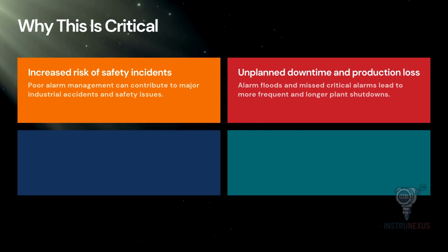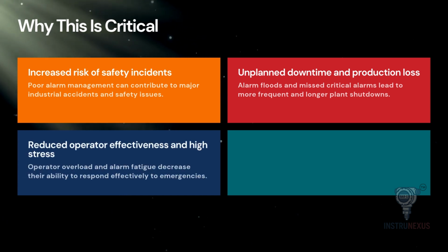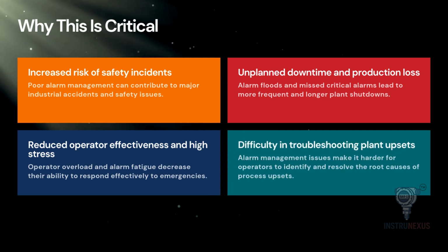If an operator misses a critical alarm because it was buried in a flood of nuisance alarms, that can lead to a plant shutdown. Furthermore, this overload causes high stress and fatigue, reducing operator effectiveness and their ability to respond to real emergencies. Finally, when the board is lit up like a Christmas tree, it becomes incredibly difficult to troubleshoot plant upsets and find the root cause of a problem.